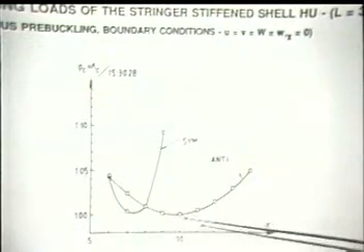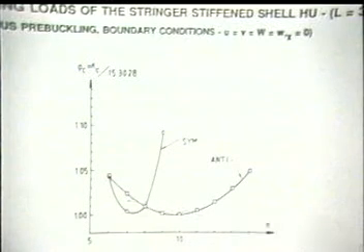The solution of the nearly simultaneous eigenvalues and eigenfunctions is done by a subspace iteration, which seems to be very efficient because we have been able to pick up without any problem buckling modes and buckling loads that were practically simultaneous.